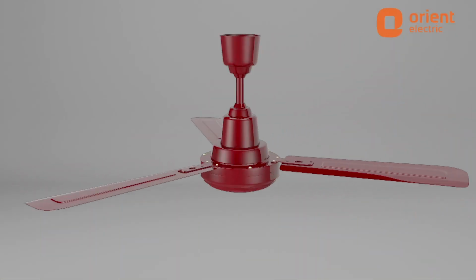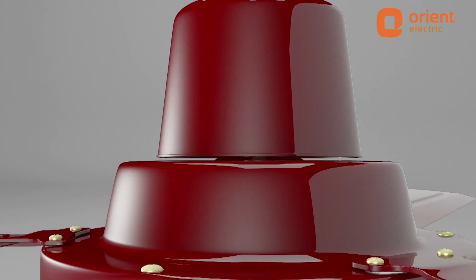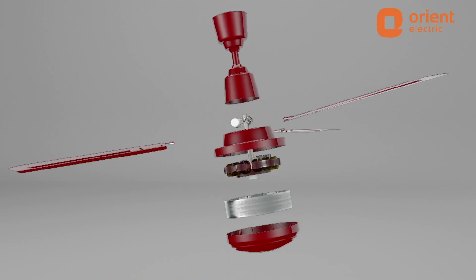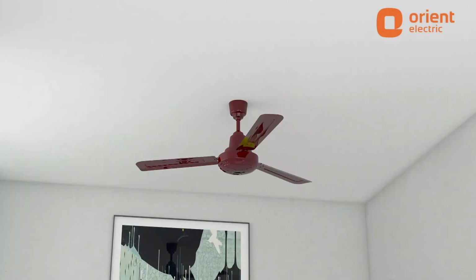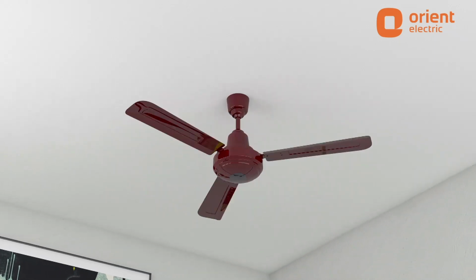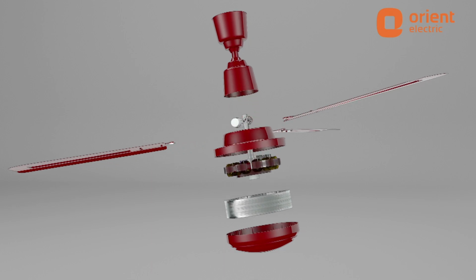There could be more than one reason why your ceiling fan is making scratching and rubbing noises. Canopy touching the top cover is a major cause of this problem, which can be solved by fixing canopy by leaving ample gap between top cover and the canopy. In case the stator is touching the rotor, you will need to dismantle the fan, readjust motor and stator, and then reassemble the unit. The scratching or rubbing noise can also be there if the cover is rubbing against polyester film or loop clamp. In this case, dismantle the fan and rectify the fault.